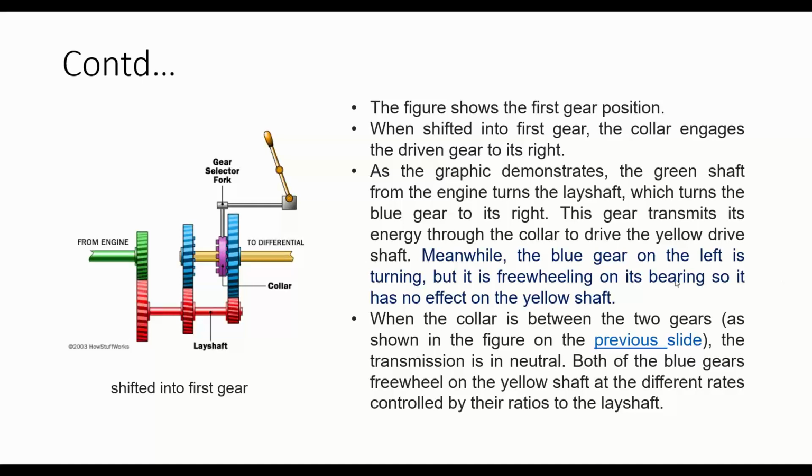You have to explain about the driver shaft or engine shaft here, the lay shaft or the counter shaft, and the driven shaft or the differential shaft. First, you have to describe these three things. Then you have to talk about the driving gear. So these are connecting gears and these are the driven gears.